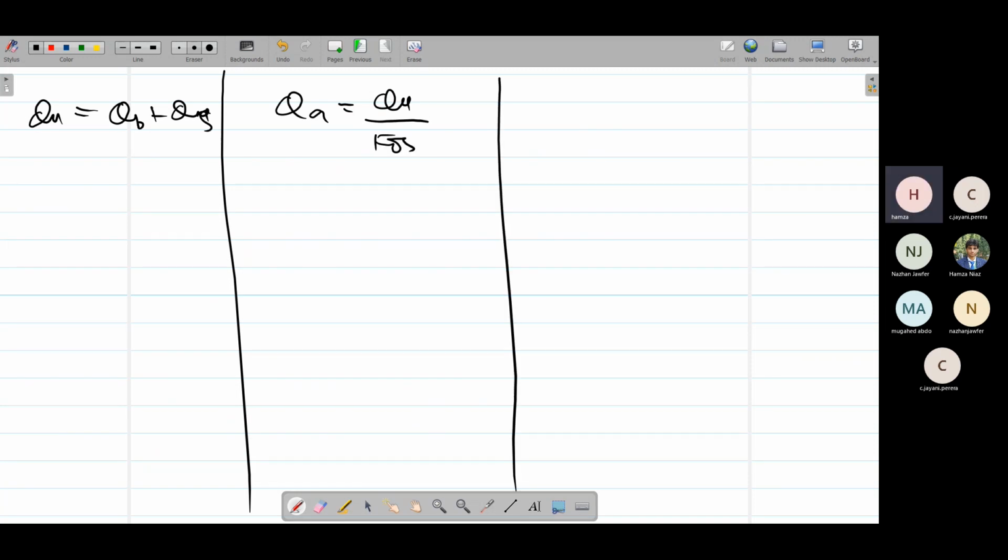And the Q in tension, the tension capacity, we can conservatively assume as 0.1 of Qu. Either this value would be given, or we can assume this as 10%. So we can take this as 0.1 times Qu, and we can get the pile capacity in tension also from this SPT test.